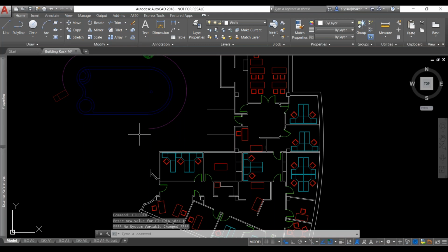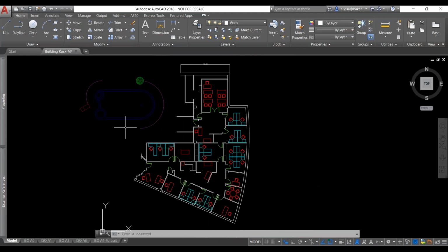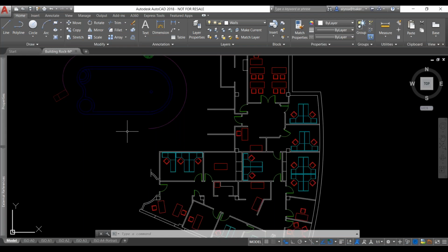Okay, cool. So there are another 2 items that we could change. Another system variable that I know of is tray notification. Often you'll see those little pop-up bubbles that happen after printing that talk about the system tray and information that you don't really want to have pop up all the time. If you want to switch this off, what I'm typing in there is TRAYNOTIFY.